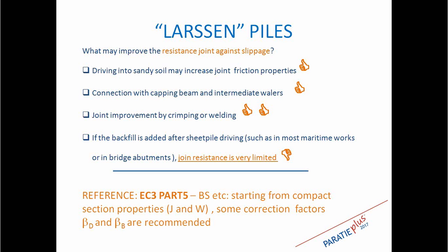Normally you may also provide a capping beam or some intermediate elements when putting, for example, tie-backs, so that the slippage is also restrained in some points.